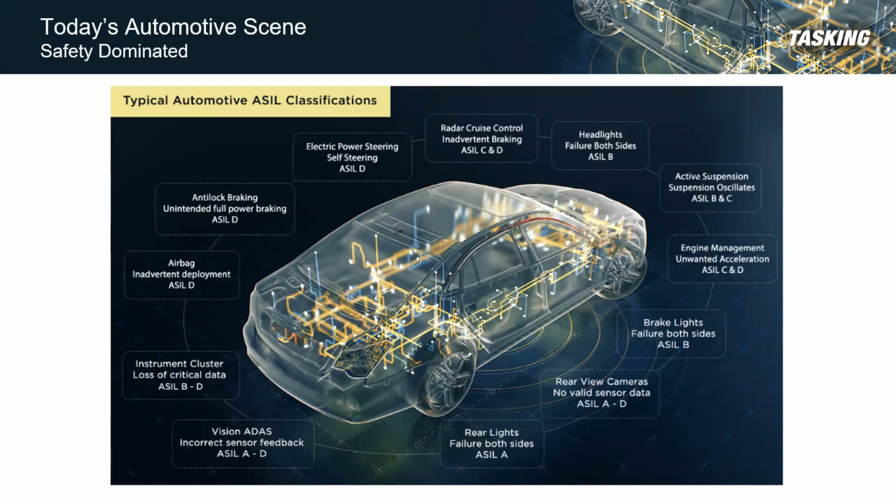As we can see by this picture here, basically all applications on today's automobile have some type of ASIL or safety requirement. Clearly, applications like anti-lock braking and electrical power steering all have very high safety ratings of ASIL D, as it's very important that we not injure our drivers by losing braking or applying inadvertent steering torque to the automobile. But you can also see applications like automotive lighting, and even with some body constraints now with seat heating and other interior occupant applications, you have some ASIL rating associated with them.